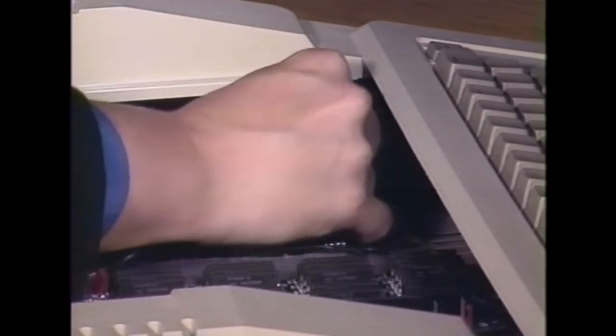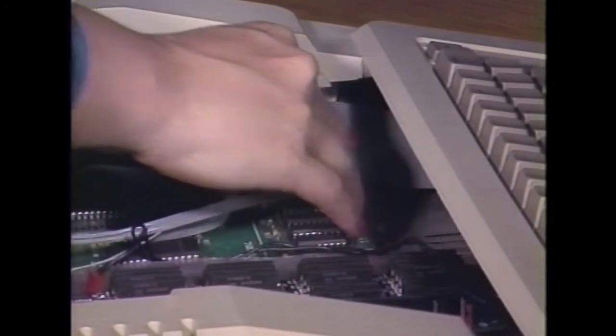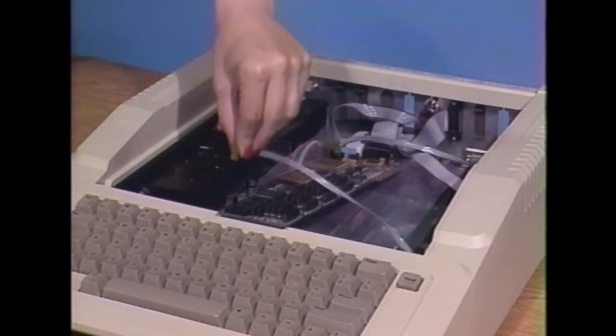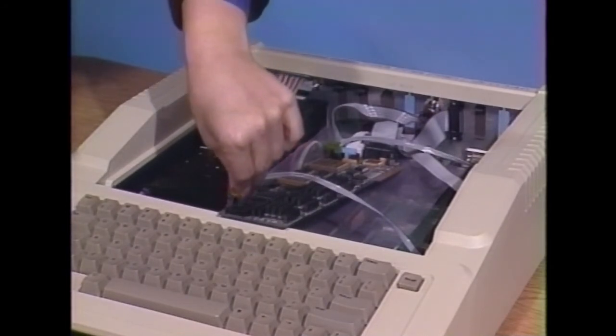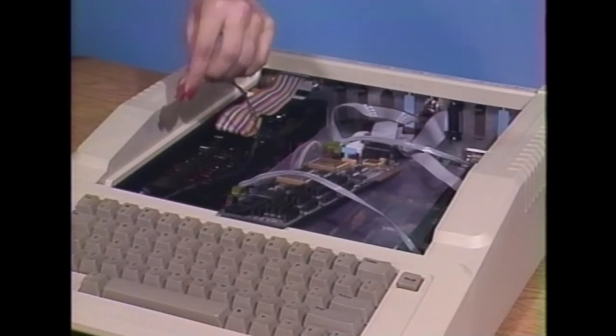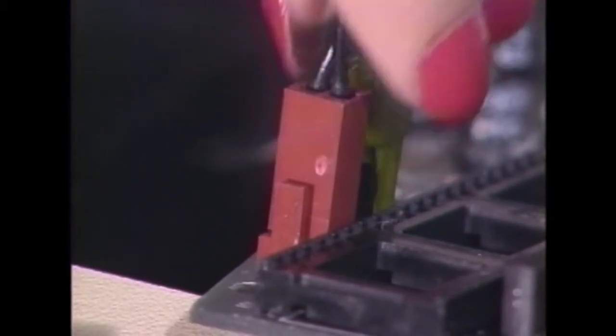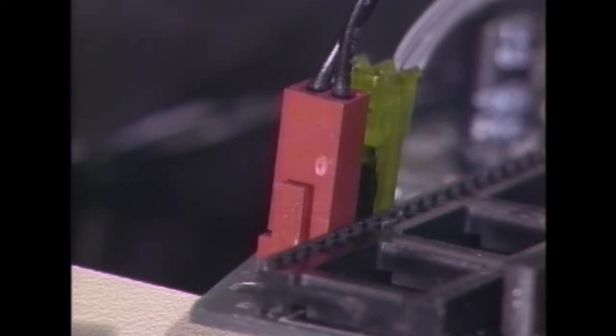Connect either end of the supplied cable to the connector at J18 on the Apple's motherboard as shown here. Make sure that the connectors are properly aligned. Connect the free end of the supplied speaker cable to one of the 2-pin connectors located toward the keyboard end of the PC transporter. Attach the connector that you have unplugged from the motherboard to the remaining 2-pin connector on the transporter.